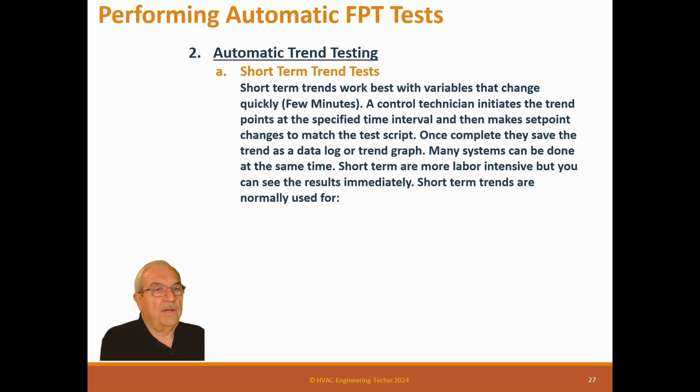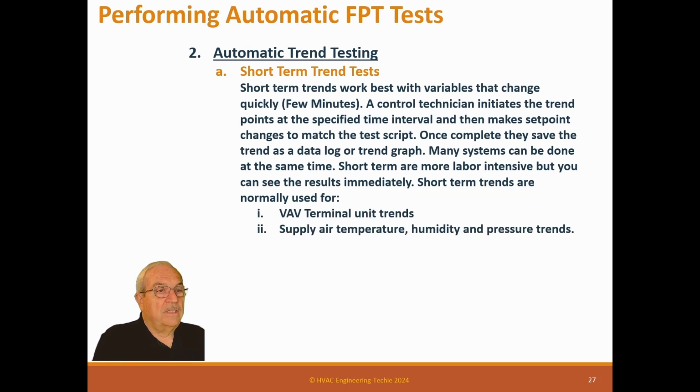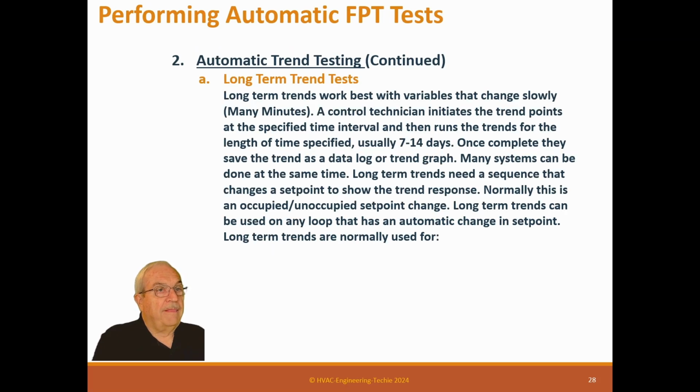Short-terms are more labor-intensive, but you can see the results immediately. Short-term trends are normally used for VAV terminal units, supply air temperature, humidity, and pressure trends, pipe chilled water and hot water temperature, pressure, and flows.